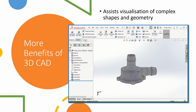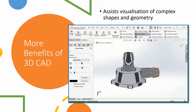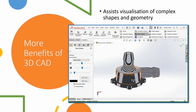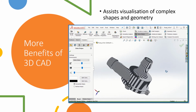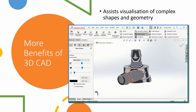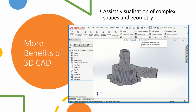Another tool is in the Evaluate tab, and we're going to look at zebra stripes and curvature. So zebra stripes allows you to see curvature very easily in a part. So there we go, this is zebra stripes on, and as I move it around you can see different elements that are in different planes will have curvature showing differently, and again whichever way I rotate this, so this enables me to see where there is bits of curvature in my part very easily. I'm going to turn zebra stripes off for the moment, and now I'm going to turn curvature on.